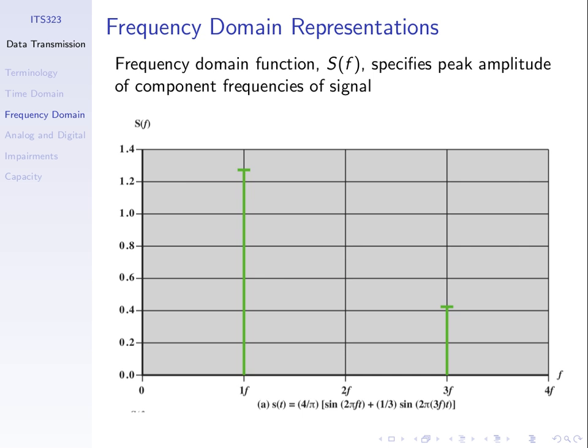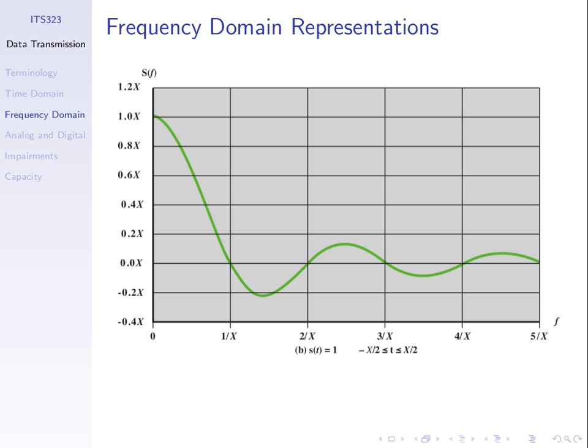What do you think the absolute bandwidth of this signal is? And it keeps going. What do you think the absolute bandwidth of that signal is? Well, it turns out it becomes infinite. That is, you can see this waveform is getting lower and lower and lower, but in theory it will keep going, getting smaller and smaller and smaller. In theory it has an infinite absolute bandwidth.